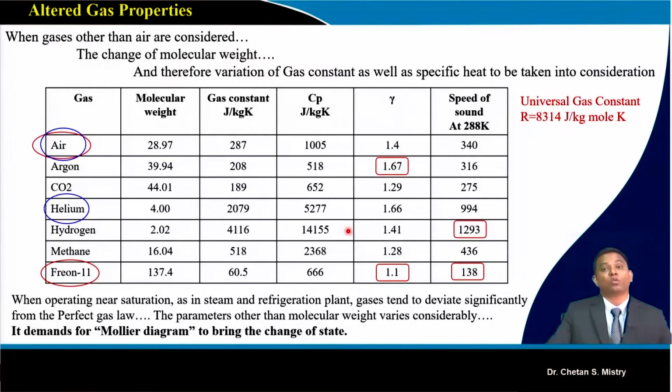Now in order to test those helium compressors, they use an axial flow compressor with air as a working fluid. That gives a benefit, and it rotates at comparatively low speed as compared to when you rotate that wheel using helium gas.